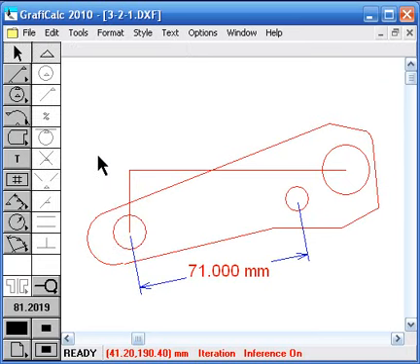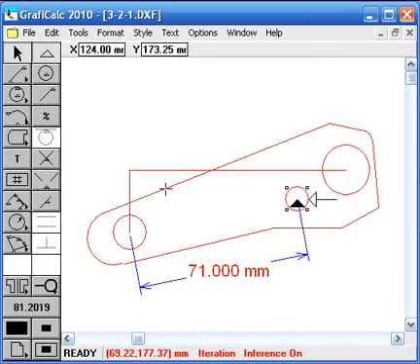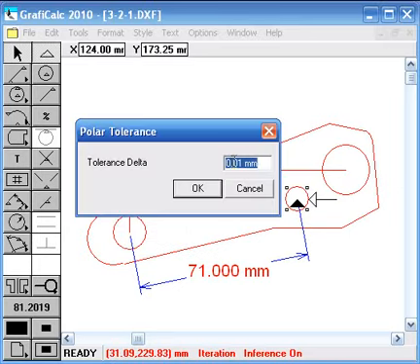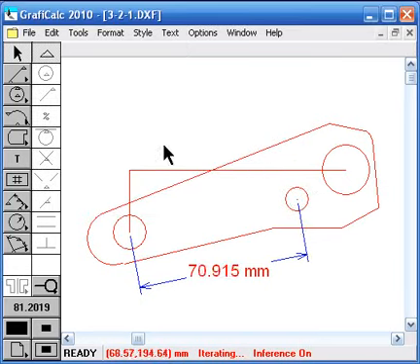Now he's selecting his manufacturing processes, so he thinks, okay, I can punch this. The welding machine has a polar tolerance. It'll be off center, but let's say 0.1 millimeters. Immediately you can see the effect on the critical measurement here. It's almost similar to watching a virtual manufacturing process going on.